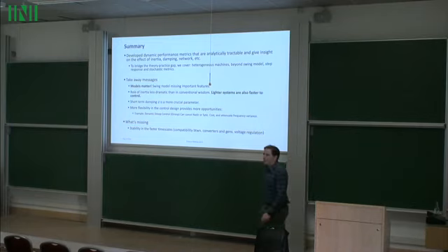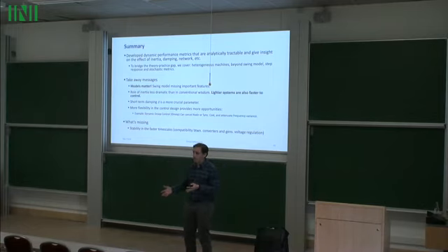What is the reason to do that? Like the Rocof? I don't know if Rocof is such an important metric, to be honest. Maybe more expert power engineers can tell me, but my understanding is that the only reason you measure Rocof is because your turbines have delay, and therefore high Rocof plus the delay of the turbine gives you a big nadir.